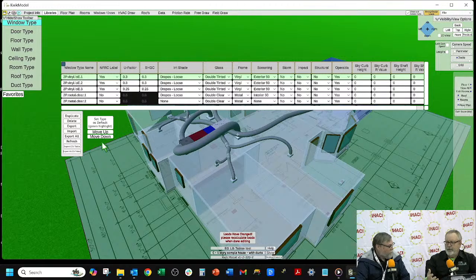Exactly. But in an older home, infiltration is probably one of the most important things. So you recommend a blower door if they're going to measure a house? Yes, absolutely, blower door every time. It's amazing how leaky houses can be. I've had up to 20 air changes per hour. I couldn't almost get a reading with it, and this is like a 1,200 square foot house.